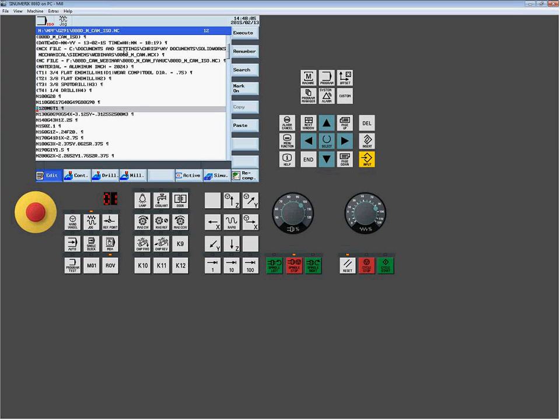To do tool change, we have tool change protocol right here for you. We have other absolute setting up our spindle commands. So this would be what you would normally set up. Now, here is your G43 offset. So here we see H1 being called out at this point.